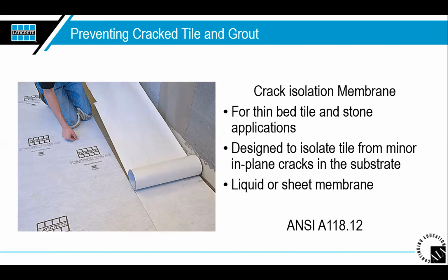A lot of times we'll hear the term, oh, I'm just going to put a Band-Aid on it to treat these existing cracks. That will not work. If you are talking about a Band-Aid type of method, there are installation instructions according to different materials that say you can just treat a crack, for example. Your entire floor may not be crack isolation, which to me, I don't know why it would ever get passed up, especially on a concrete, but even wood installation as well. But I have seen scenarios where they'll actually only treat specific cracks.